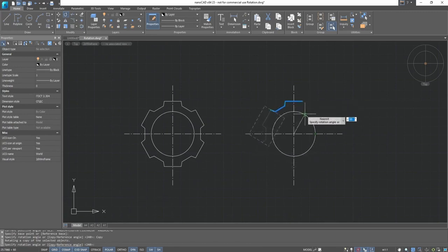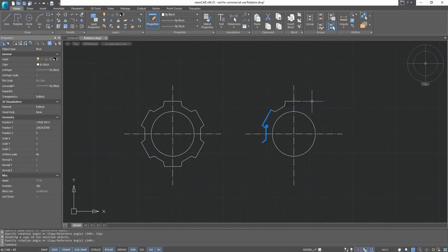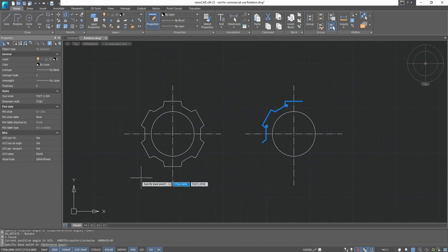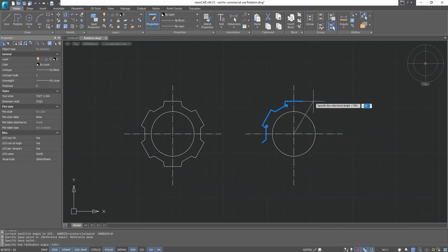Using polar tracking, we will then show how to work with the reference angle. We rotate our section of the figure. This is the element we got. Next, we can select both objects, and they will then rotate together. Now, let's rotate using the reference line. To do this, we need to specify a key point and the intersection of the axes, then set the reference angle, and confirm the final action. New reference angle.